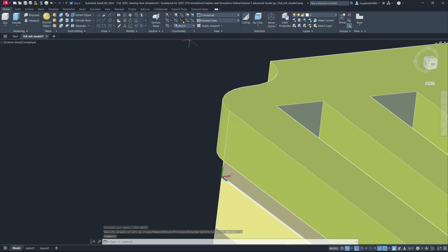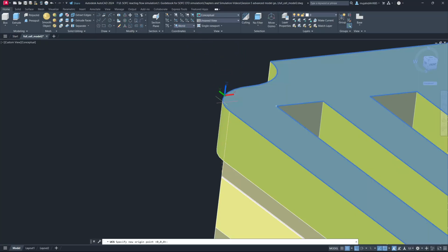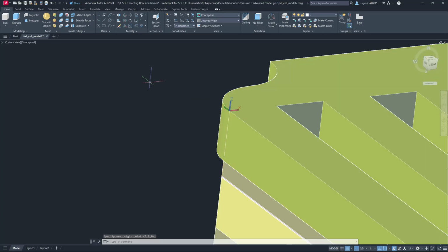So we will just move along until this point, and in the xy coordinate we should rotate about x. Yes. Again rectangle 0, and the height of the interconnect is 0.5 mm, so giving 19 comma 0.5.